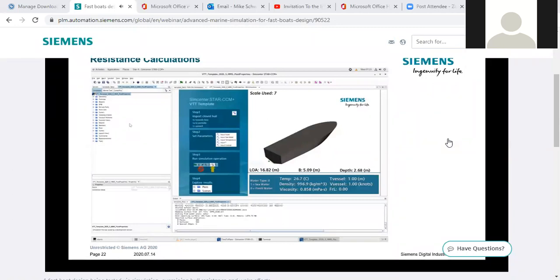It can be simple sweeps, so it could be an input of desired runs, or it could be anything to a full optimization. The nice thing here is that you can set up what you want to run. Then the software will run all the jobs for you. You don't have to set up a new run by hand each and every time you want to change a boundary condition.